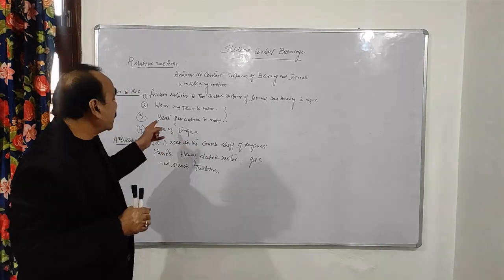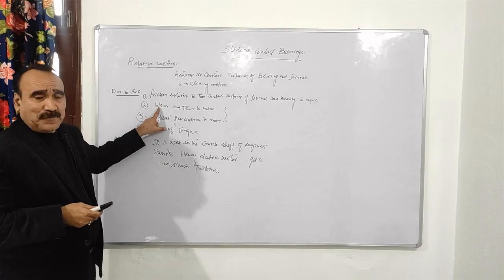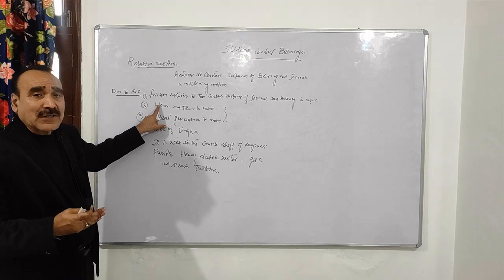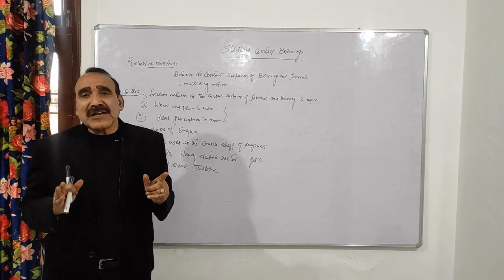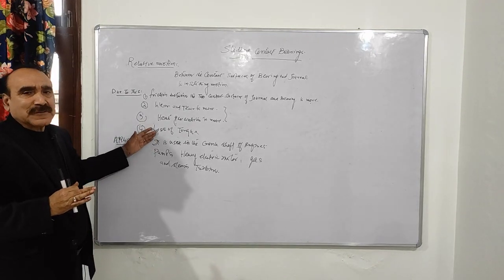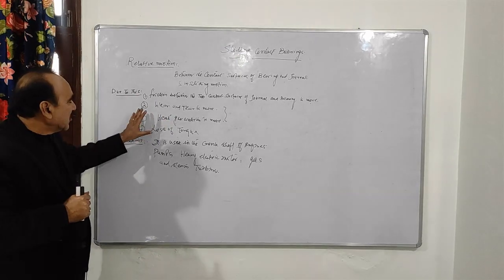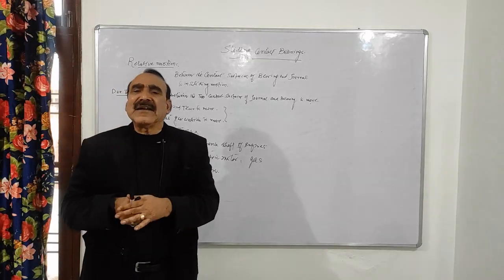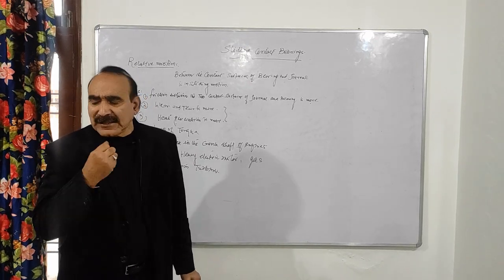But in case of the sliding contact bearing, you have seen that these things are there because the motion is relative motion between the two contact surfaces, that is the journal and bearing. That motion is the sliding motion. And when there is a sliding motion, these things are more. So in order to reduce the effect of these things, we need the lubrication here, right? So this is about the sliding contact bearing, and now I have also explained what is the difference between the rolling contact bearing and the sliding contact bearing.